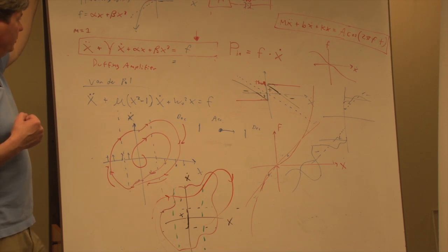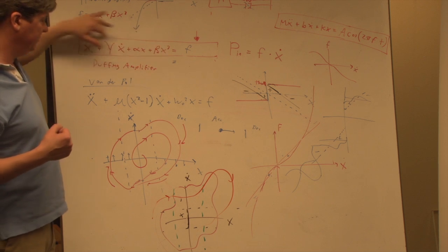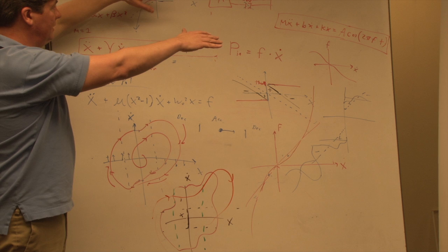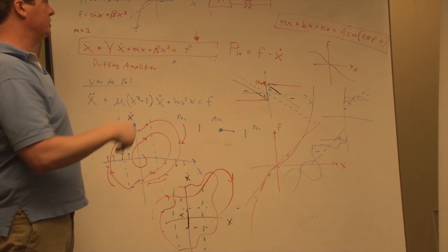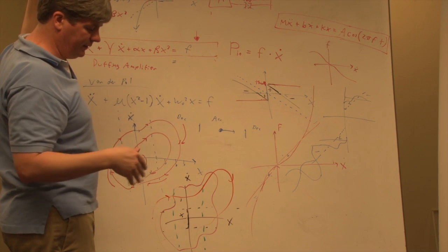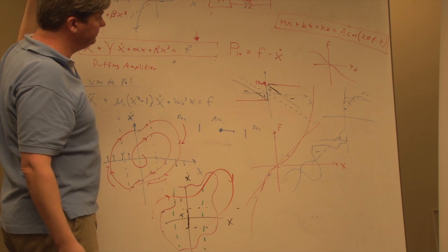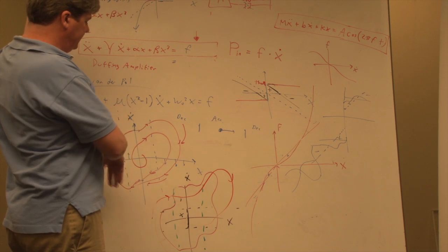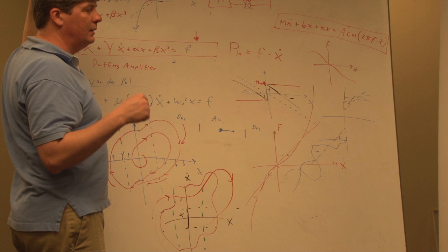What we're trying to do in FastRunner, this is a very simplified version, is have a bunch of mass, a bunch of springs, a bunch of dampers because they're going to exist, and then drive one of the linkages such that you get nice nonlinear oscillation where the harder you drive it, the higher the frequency and the higher the amplitude the step is, and drive it in such a way that it just naturally finds these limit cycles rather than trying to force it with a sine wave.